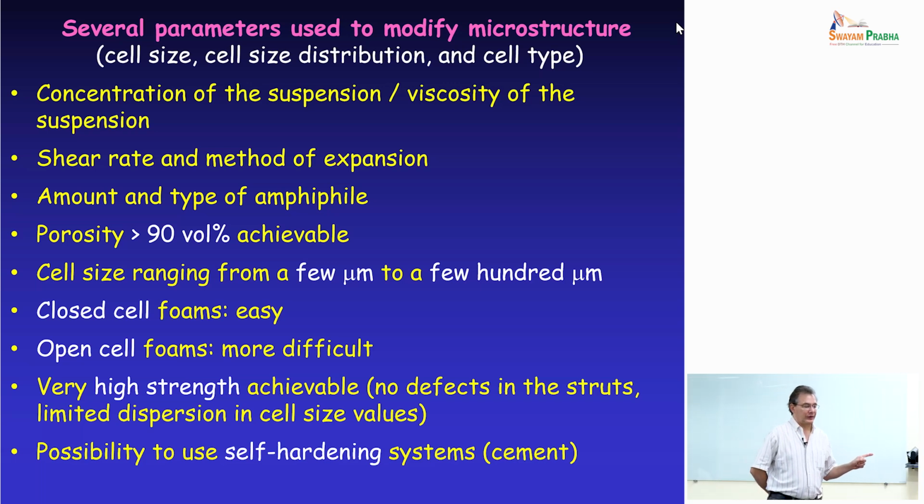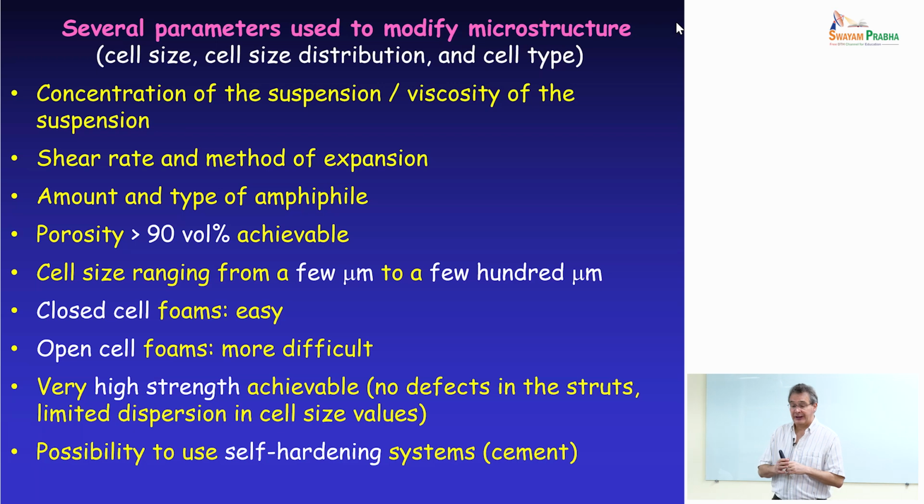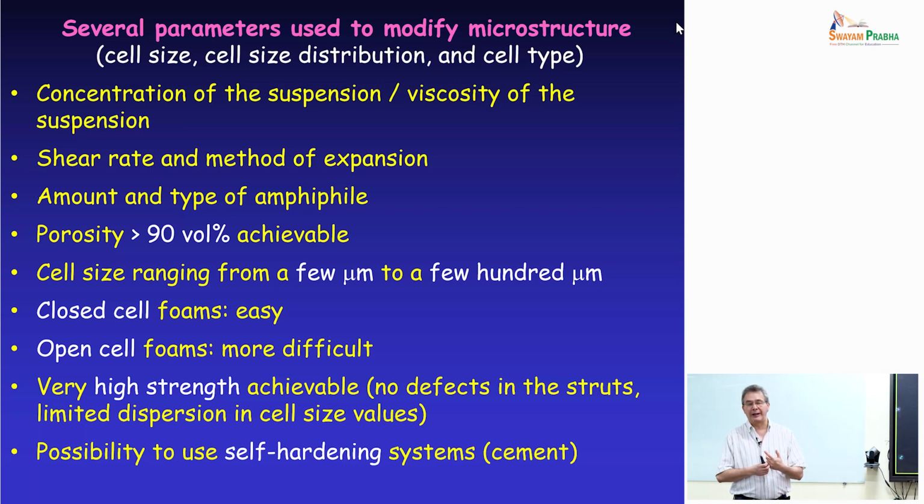One characteristic of this approach is that the functionalized particles sit preferentially at the interface between the liquid and the gas. And this leads to closed cell foams. And a lot of applications for ceramic foams or porous ceramics require interconnected porosity. So this is a little drawback of the approach. It simply means that this is a very good approach for making specific components, for instance, for thermal protection. A little bit less favorable for making open cell components.